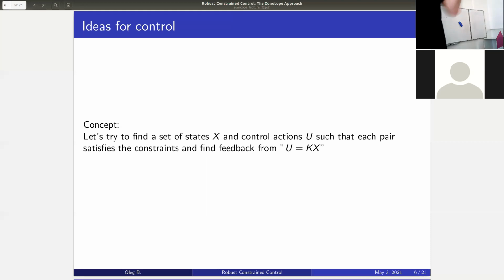For example, in MPC, we can very easily find feed forward for one point. And here we can take several points, find feed forward for each of them, and based on it, find feedback gains. It's a very different and at first very non-intuitive concept, but it has a lot of advantages because you think not about feedbacks and gain values, you think about trajectories and how a system really moves.